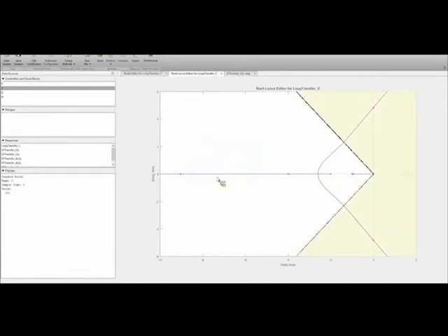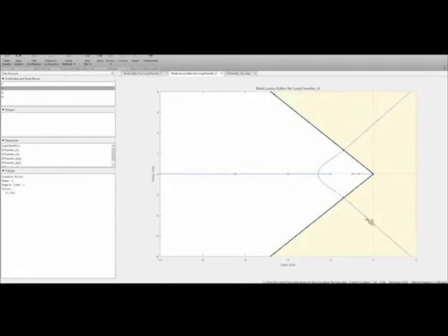All right, so this is going to put markings on our plot for us. If we call the yellow region an exclusion zone, we want to make sure that no closed loop poles are in this region. This gives us an idea of where the closed loop poles should be. So via the software tools, I can just move these such that they're inside. Now you notice that we don't have as good a pole zero cancellation here anymore, so we're going to have aspects of our response that look somewhat like a first order response, because that's what a real pole looks like. But we see that we're going to have significantly lower overshoot in this example, because all of our closed loop poles are in this region where we get less than 15% overshoot.